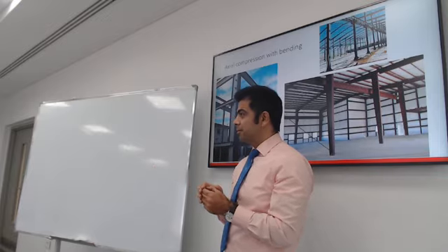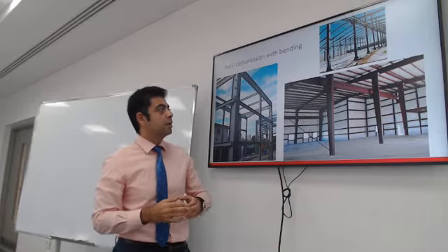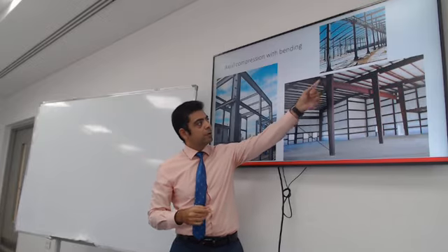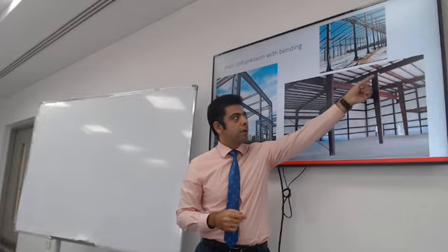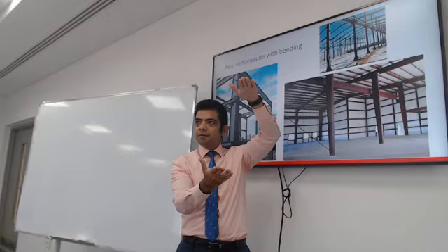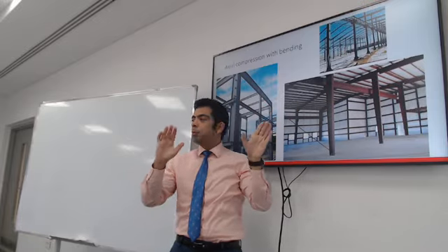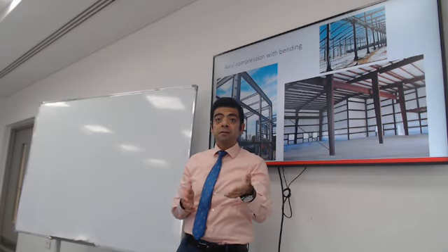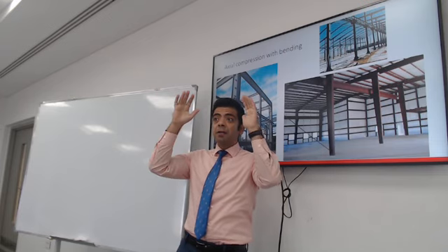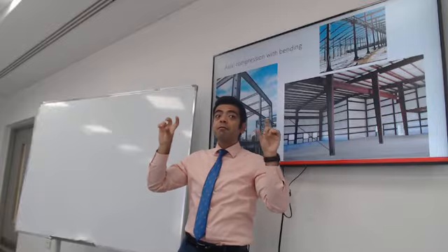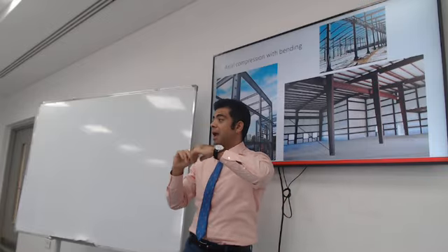A moving crane, yes. I actually have a picture of exactly that. So this is a column, and if you look closely at the joint above, this is a very big, significant joint, because as a matter of fact, this is designed as a portal frame. So as we discussed in structural analysis too, you can have a frame resisting gravity load, and it will have moments in the column. So this column will be designed for axial load and moment.